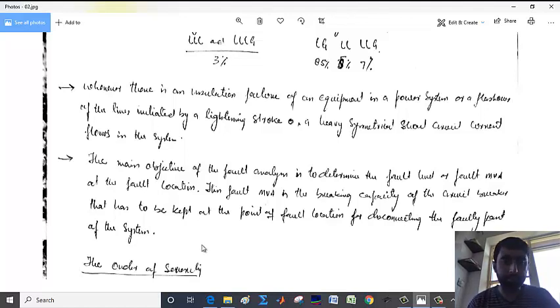As we know, we cannot mitigate the fault, but at the fault time, we can introduce a circuit breaker that opens the circuit so that the fault is not fed from the source, or we can say the fault may be cleared after that. So to install a circuit breaker, we need to first calculate its breaking capacity or fault current carrying capacity before installing it.